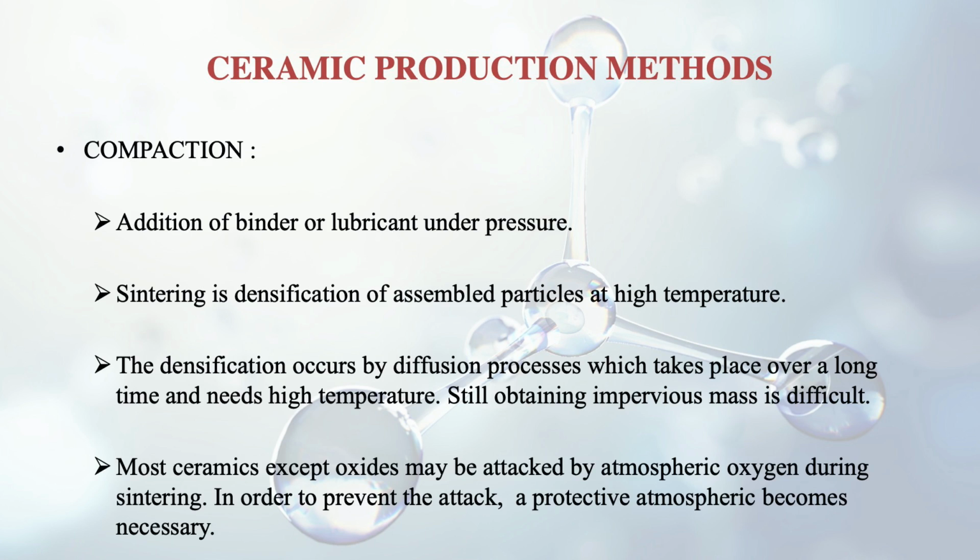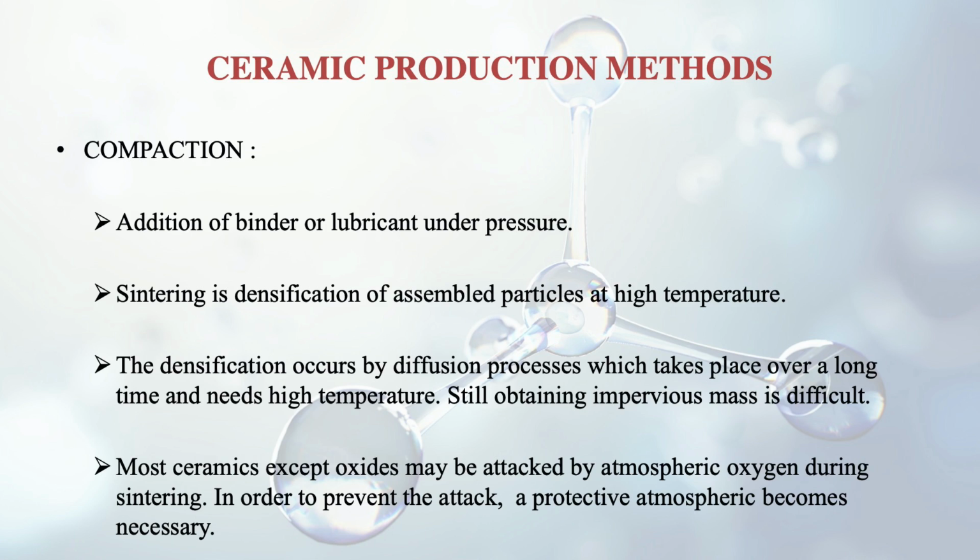Most ceramics except the oxides may be attacked by atmospheric oxygen during sintering. So this is one difficulty that we face during the sintering process: this ceramic is not that resistant to oxygen, so it may be attacked by oxygen. So we have to create a protective atmosphere to get a better product.